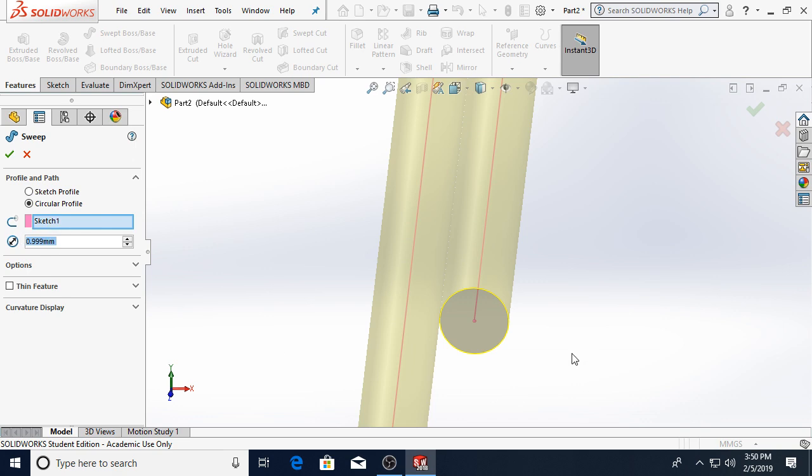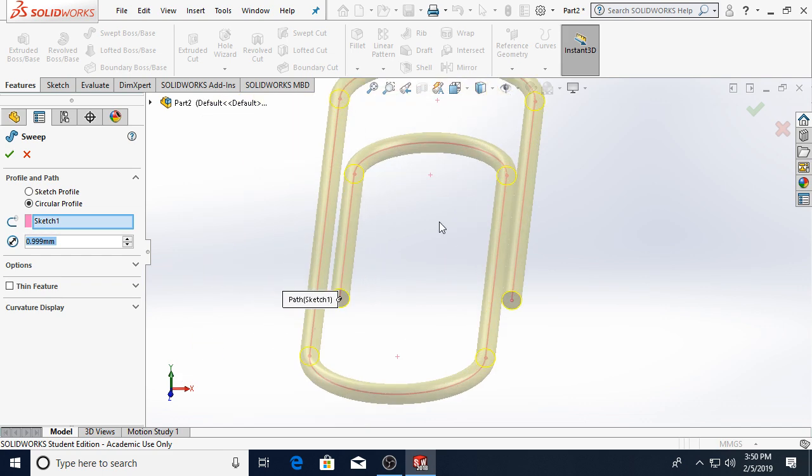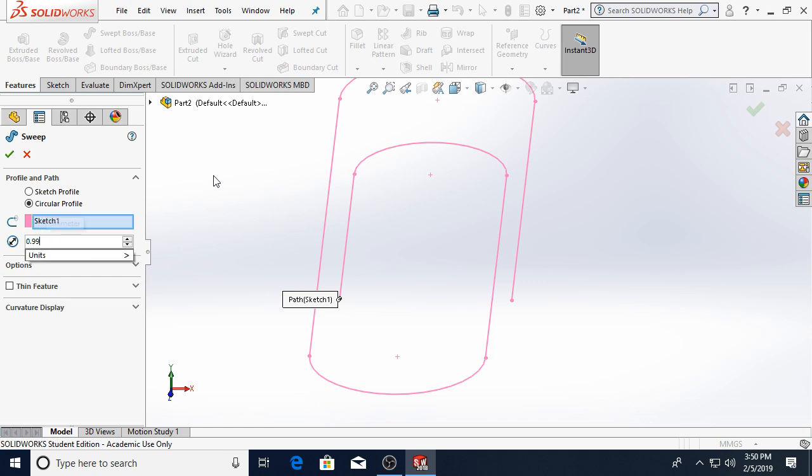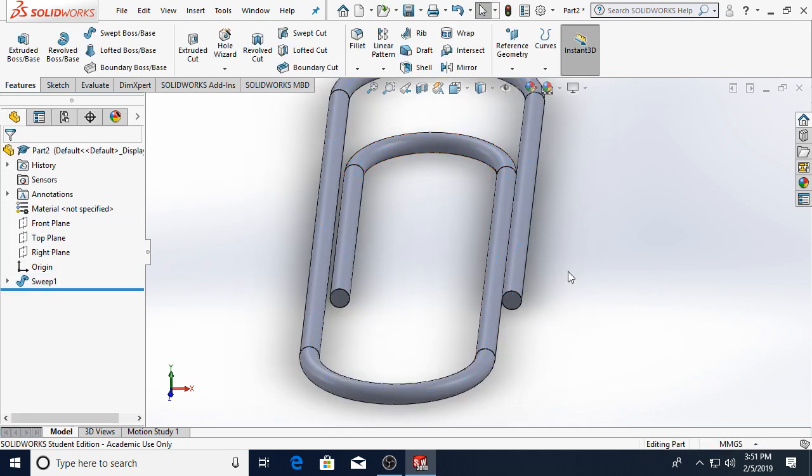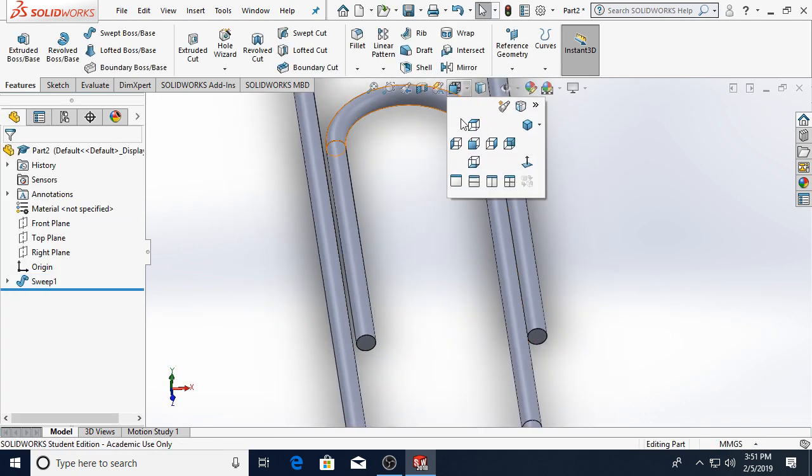So in this case, I would either have to create a slight offset between these two lines. Maybe instead of 1 millimeter, I can make them be 1.0000000000001 millimeters. That would work. Or I could make the diameter of this circular profile a little bit less than 1. SOLIDWORKS only uses about 6 decimal places for precision here, so anything more than that, and we effectively have 0.9 repeating, which is 1. So, a little bit less than 1 millimeter gives us a paperclip.